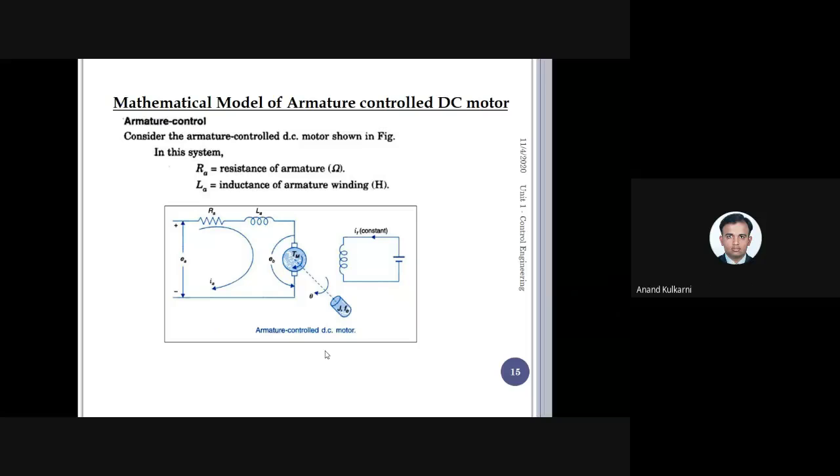Okay. So in an AC induction motor, as in any electrical motor, there are two things. One, you have to generate the magnetic flux, and second, you have to supply the power to the armature, or electricity, so that the motor will start running. In small motors, like the toy motors you might have seen in childhood days driving a small car, if you break open that motor you will find a magnet there. These are called permanent magnet motors.